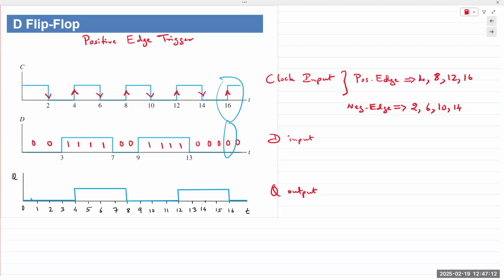Yes. Is the Q output at the start being 0 something that would be given, or do we just assume that? So the question being asked is, what about here? Falling edge, right? So we don't know. It should be Qn minus 1. The point being, from the information that we're given, we don't know. This would be unknown. It will simply be Qn minus 1.